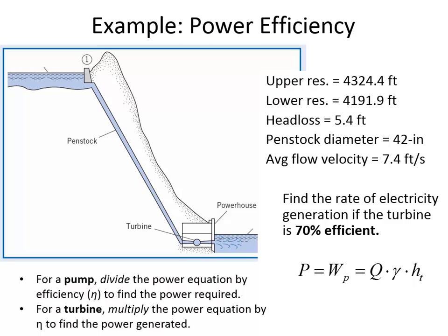Head is the amount of energy that exists in a hydraulic system, and if we had a pipe that we tapped with a piezometer, the water level would rise to a certain elevation equal to how much head there is in the system. The same thing is true of static conditions, that at the turbine there's a certain amount of head available for the turbine to extract. And this is how much we're going to have the turbine extracting.